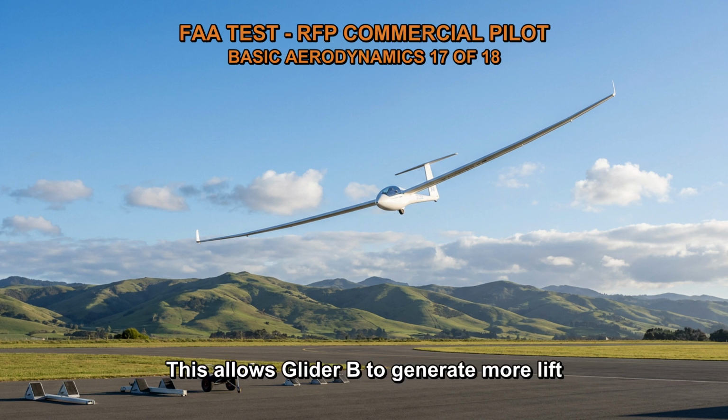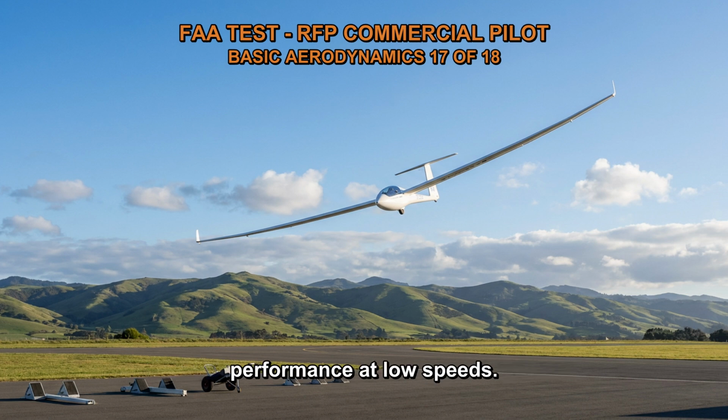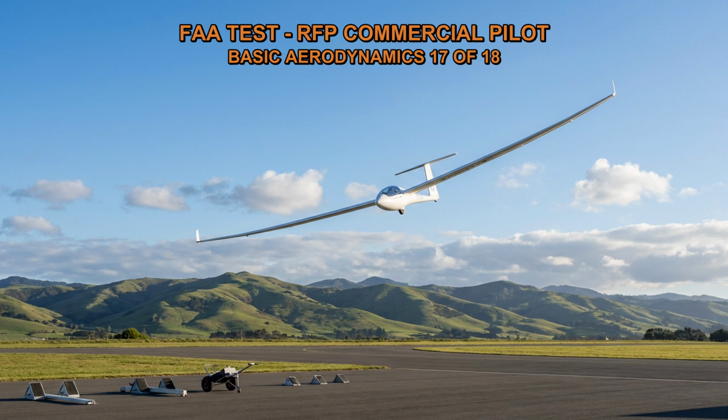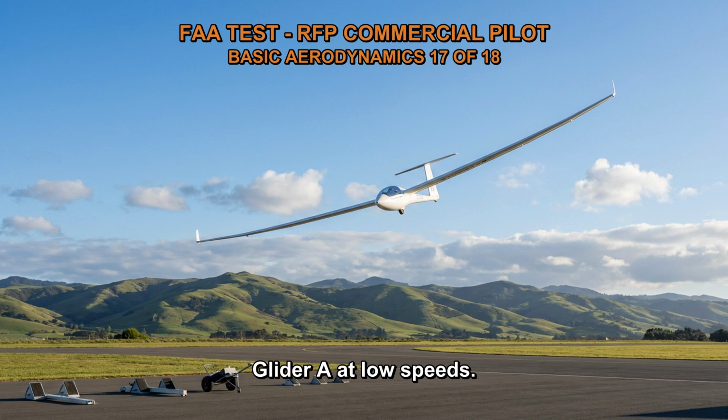This allows Glider B to generate more lift for a given wing area, resulting in improved performance at low speeds. It can maintain a higher lift-to-drag ratio, allowing for longer glides and better overall efficiency. Therefore, Glider B with its higher aspect ratio will generate greater lift with less drag than Glider A at low speeds.